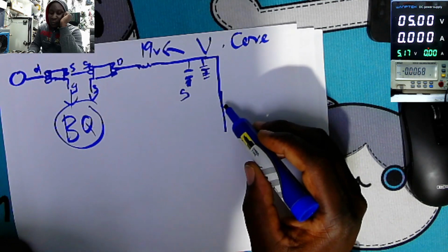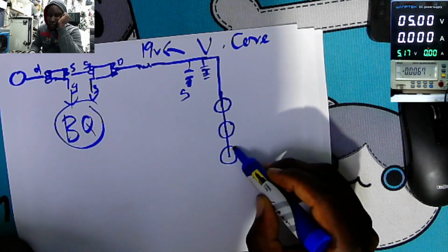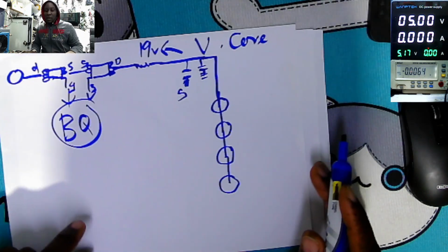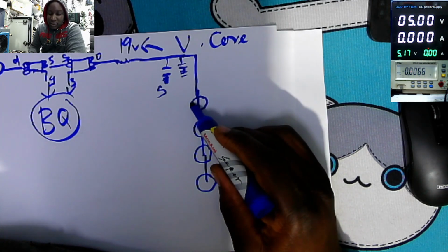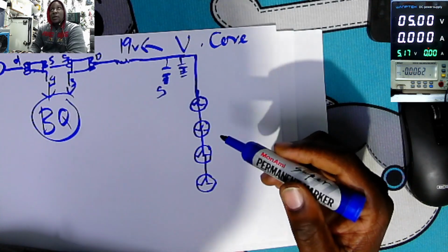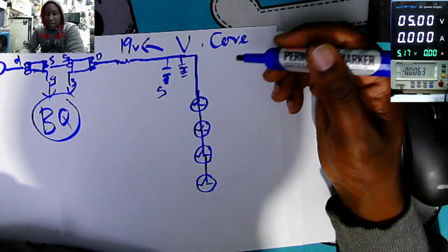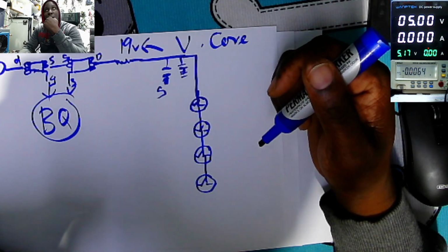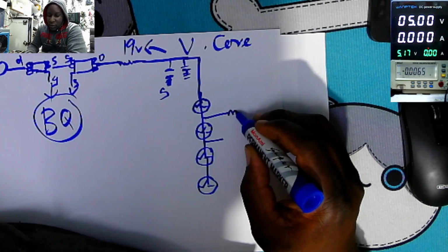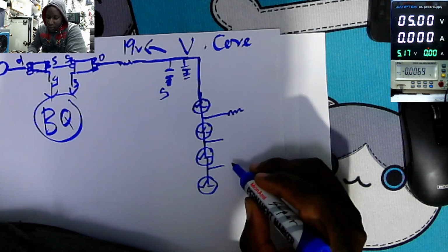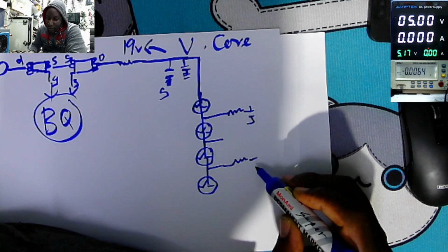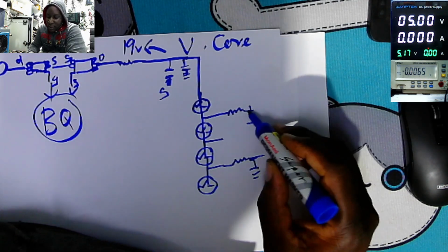And here we have 4 MOSFETs on the vehicle. Those 4 MOSFETs, they are switches. Just take these MOSFETs as switches. They are switching devices. The other MOSFET is connected on the 19 volts power line. The other ones are connected on the ground. And here we have coil, like 2 coils. And we have some output capacitors, electrolyte ones. This is an electrolyte capacitor.